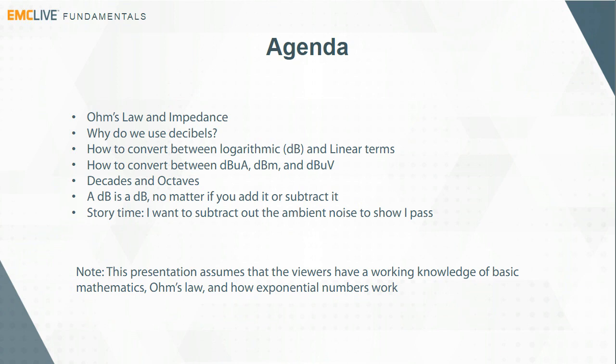We'll talk about why we use decibels in these measurements, and how to convert between logarithmic and linear terms. We will talk about how to convert between dB microamps, dBm, and dB microvolts. We'll hit on decades and octaves. We'll touch on how a dB is a dB no matter how you slice it. So if you have a dB in power, what does that dB do in field?